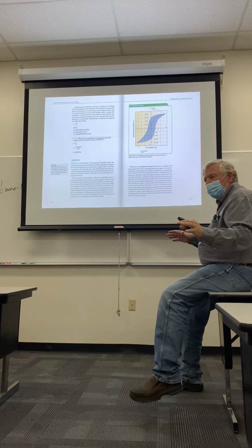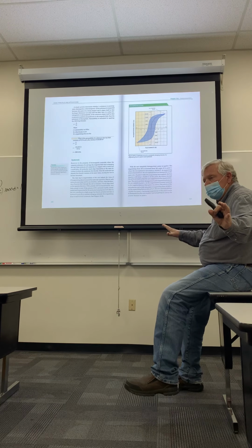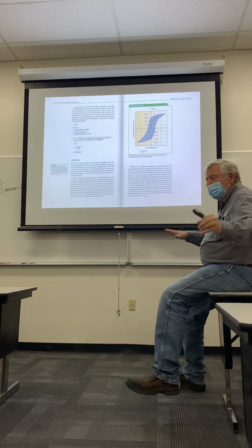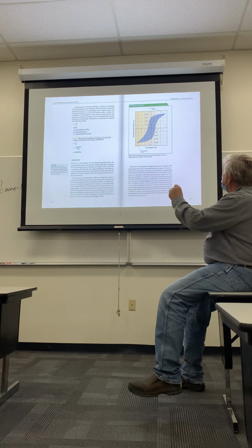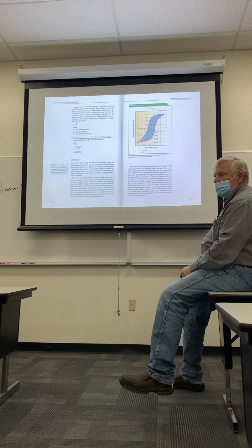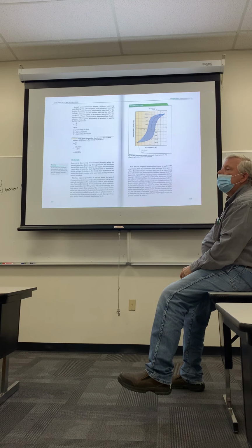The saturation point can take no more magnetizing force. It's reached its maximum level of magnetizing force. On this particular chart, at this point here, which they call point A, it's at about 16,000 gauss. So hysteresis is a relationship between flux and magnetizing force.